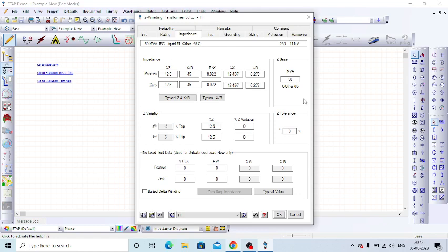So we consider the positive tolerance for the load flow study, and the negative tolerance for the short circuit study. In the short circuit study, we are calculating the fault current at the particular buses. When we consider the negative tolerance, the transformer offers lesser impedance. Let's say if the tolerance is 10 percent, then out of the 12.5 percent, 10 percent will be the negative value.